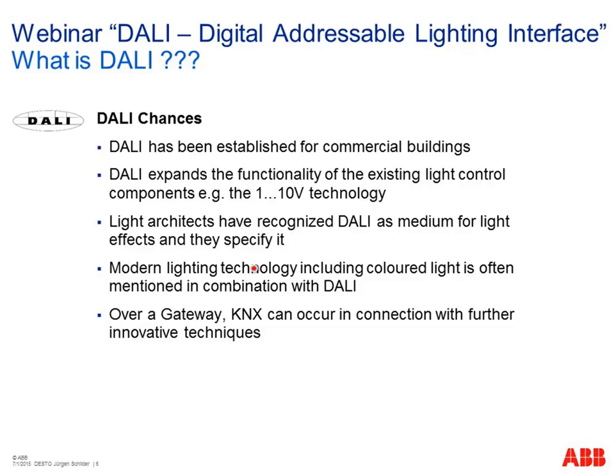LED lighting comes very often, very often used together with DALI. And as you know, gateways also exist from DALI to other systems. In our case, we have, of course, our DALI KNX Gateways, which allow you to do bigger projects, especially if you talk about big commercial projects. Then you normally have a gateway to a superior system in use. In our case, of course, we prefer KNX. But it's not only related to KNX; gateways to DALI also exist for other superior building automation solutions.